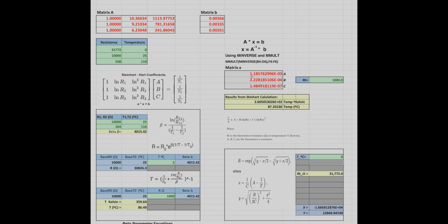And we have our thermistor, our resistor to ground. We're going to call this RS. We have our 10K here. We're going to call this RT. Or this could be 5 volts, but the voltage is known. This is essentially what we're saying there. And we're going to go into our A0, which is our Arduino ADC.